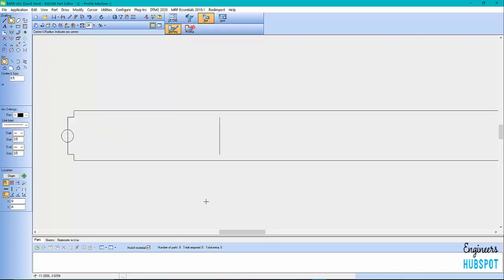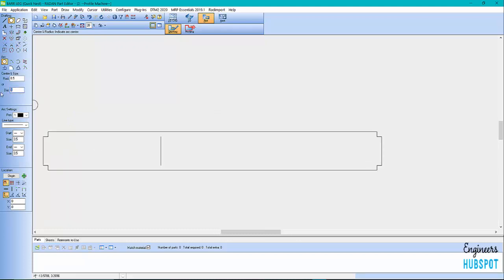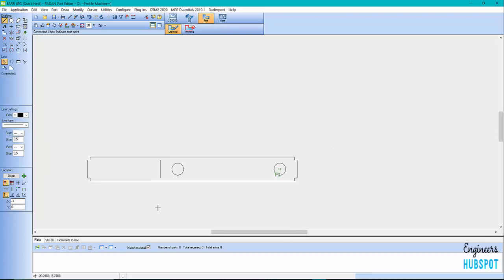And then we can come in here and say, okay, I need a 2-inch hole, and I'm going to go origin. I'm going to go from here, and we'll come in X 3.0, right, and then here we can select origin again, and we can come here. I'm just finding a midsection point, and then I'll just go minus 3.0, right, so that's where my 2 feet go on the bottom, and then we should have a sketch.